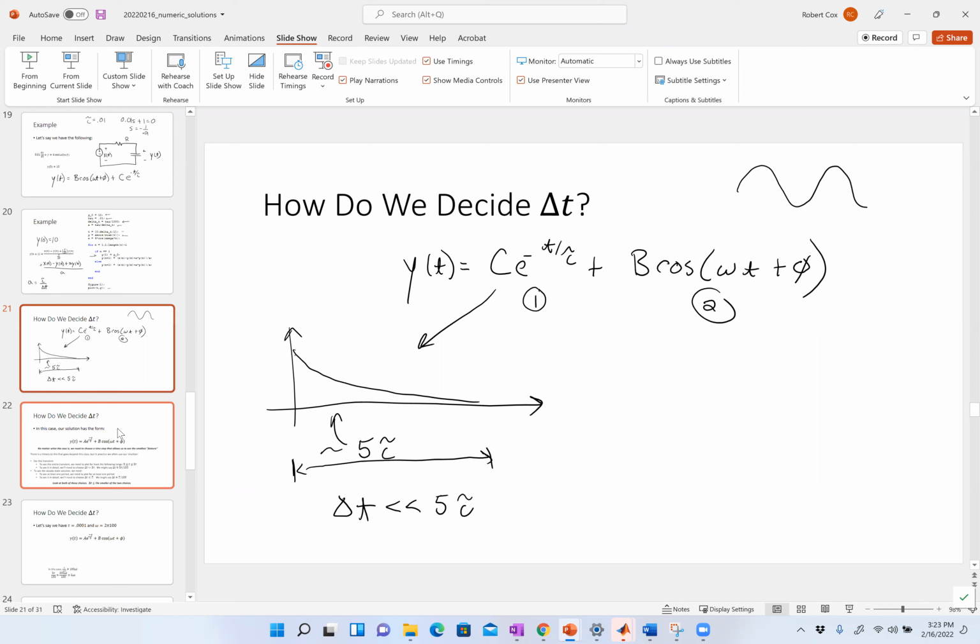So it's 100 times bigger. So I think it's shifting to the left or shifting to the right by Yeah. I mean, you're just basically shifting the decimal point a couple of spaces to the left, right? So basically, the way I think of it is delta t, if it's 100 times smaller than 5 tau, then it's 1% of 5 tau. That means in each time step, I would advance 1%. Okay, it's kind of a reasonable way to think about it. Now, that's the way to think about this transient.